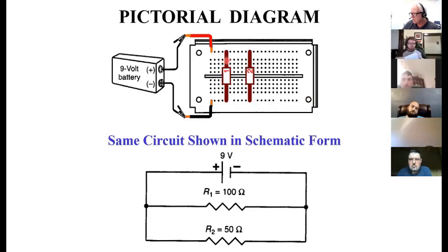So now I've plugged in these resistors, one at the top here at positive and one down here in the negative. And I've taken another one and done the same thing. This is what it looks like in the real world. This is what it looks like represented with the schematic. Everything on this side is common. You can visualize, and you should visualize, it as being a single point. This is just the same as if I were touching directly right there. And this is the same electrically as if I were touching right there.